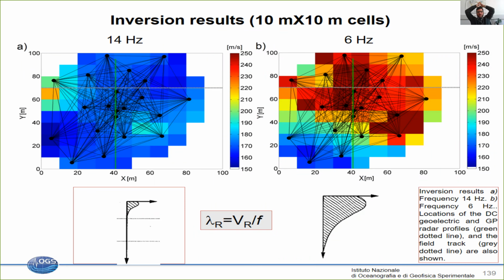Yes, in principle, yes, you can do it, but you can also go to very, very shallow, maybe for smaller distance, because then you will lose the signal before. But it depends how deep you want to go. So 14 hertz, just make a calculation. I just exaggerated to make it a little bit simpler. In this case, it's 150 meters, right? So it means you have nearly 10 meters wavelength. So in this case, you are investigating the uppermost 5 meters, more or less.